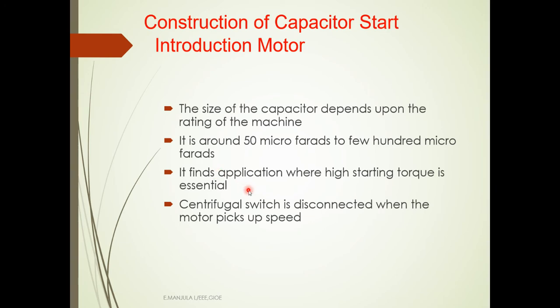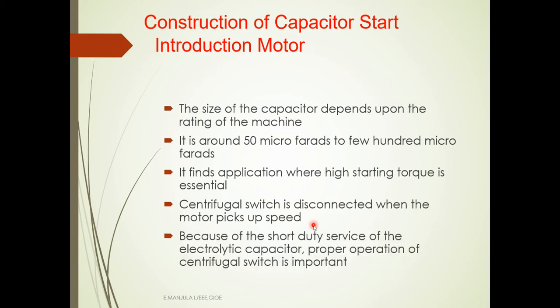So it is mostly used where there is a high starting torque requirement. The centrifugal switch is disconnected when the motor picks up speed, which means the capacitor also gets disconnected. Because of the short duty service of the electrolytic capacitor, proper operation of the centrifugal switch is important.